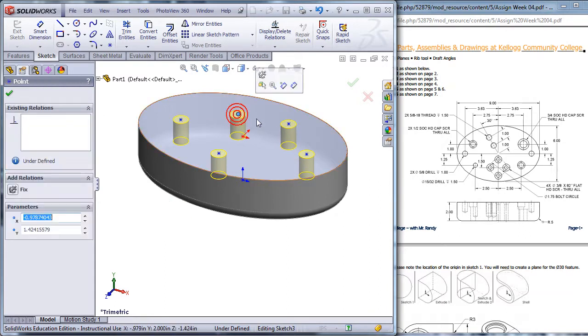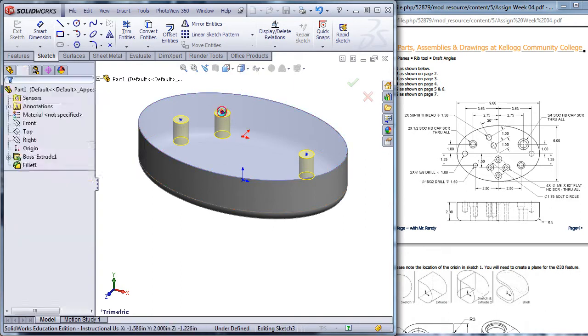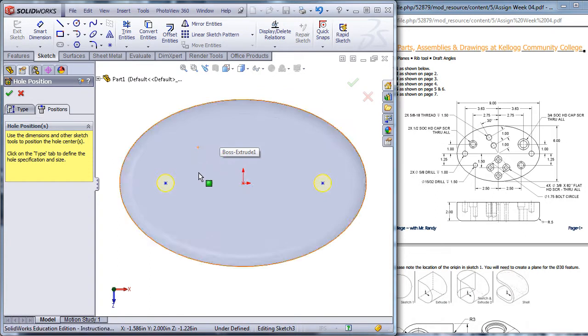Well, I don't need these holes. So I can just delete those points. So as you're working in this sketch inside Hole Wizard, anywhere you want a hole, use the point tool and just click a point. Of course, then you're going to have to define it. And that will give you a hole. So I've put the 2 holes in. I'm going to go normal 2 here.